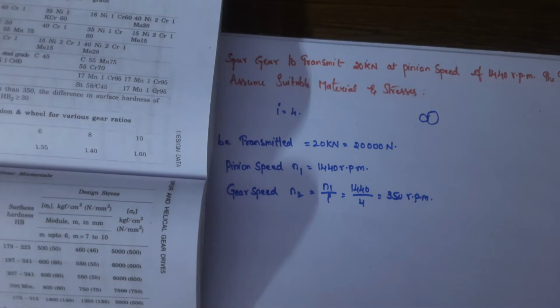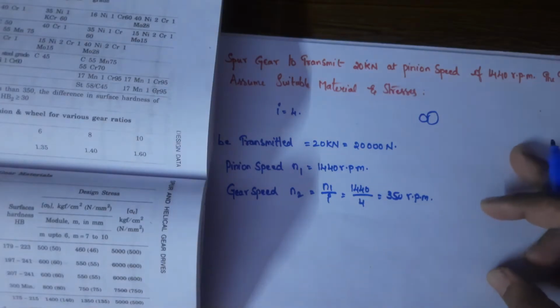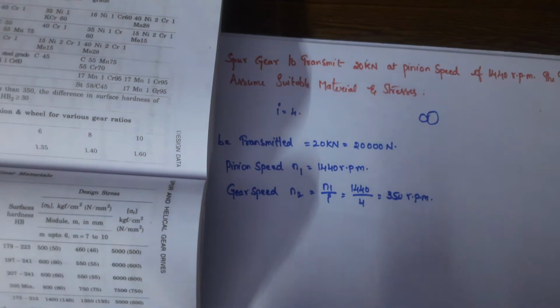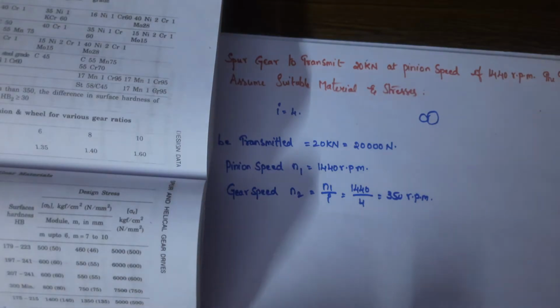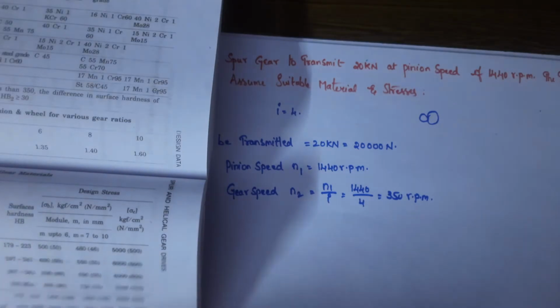As the pinion faces more loading than the gear, we have to select a high strength material for the pinion and a low strength material for the gear. Otherwise, if the life of the gear is mentioned in the question, we have to do the procedure in a different manner and select the material based on life conditions. Pinion and gear materials can be the same under some conditions, which we will see in the next question. Now we are going to design a gear without any life conditions.